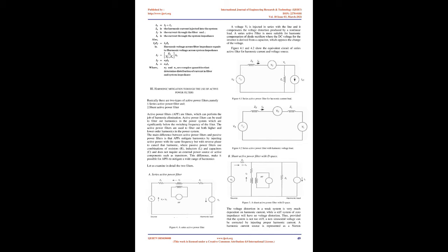Typically, a high-pass filter is modeled as a linear time invariant system. In the field of audio engineering, it is often called a low-cut filter or a bass-cut filter. High-pass filters have many applications, such as DC blocking from circuits vulnerable to non-zero average voltages or radio frequency systems. They can also be used in combination with a low-pass filter for the production of a band-pass filter. Mathematical explanation of a high-pass filter is given below.